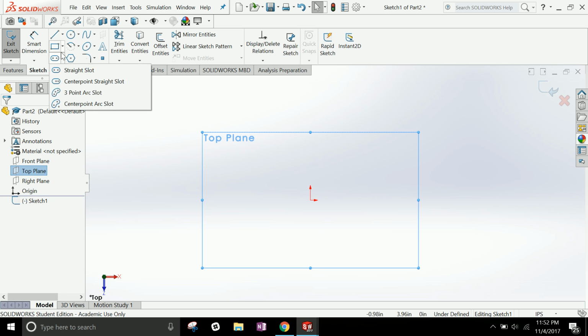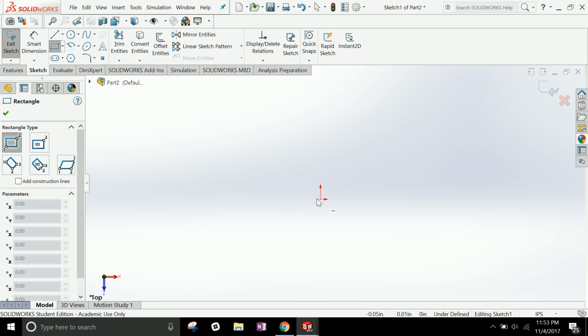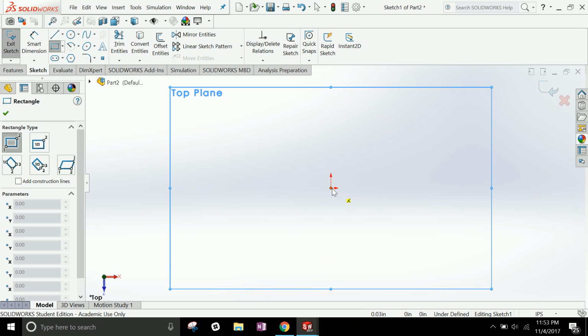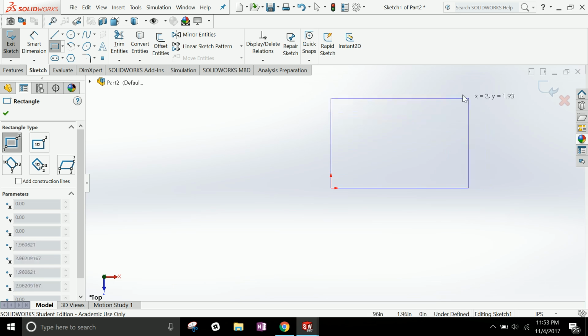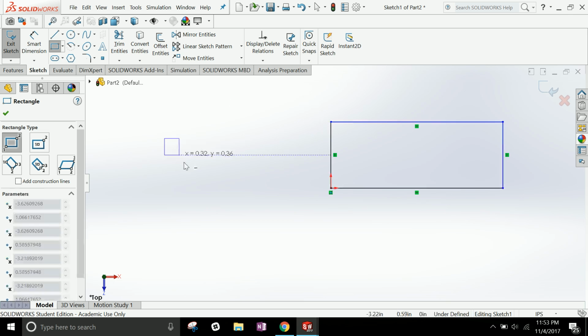So I'm going to insert a corner rectangle. As you can see, whenever I'm right over a point that's perhaps of interest, like the origin, it's going to turn orange for me and give me the little yellow coincident icon. I'm going to click, so I know I'm right there. And I can drag it all around, and I can make this rectangle. So I've now made a rectangle. Now it's ready to go. It's really easy.